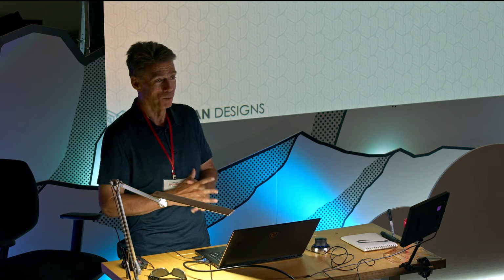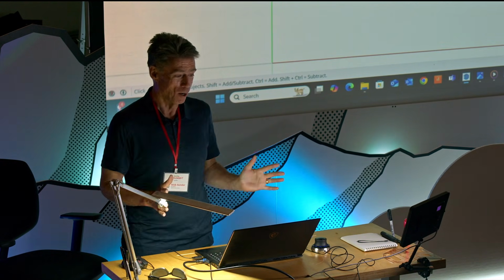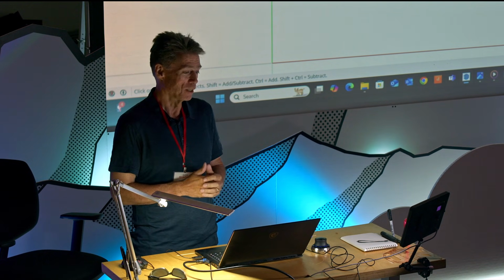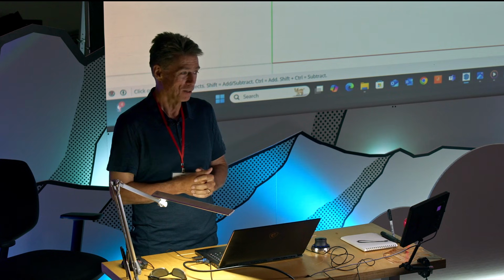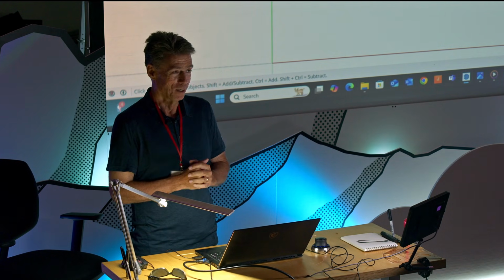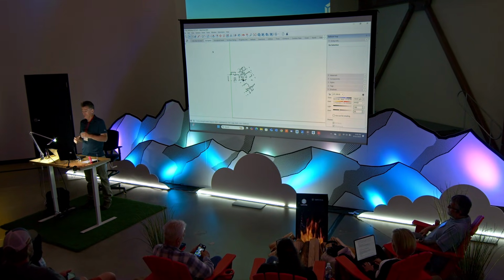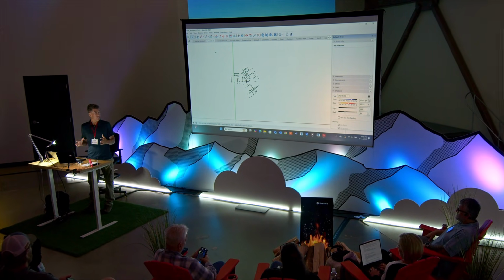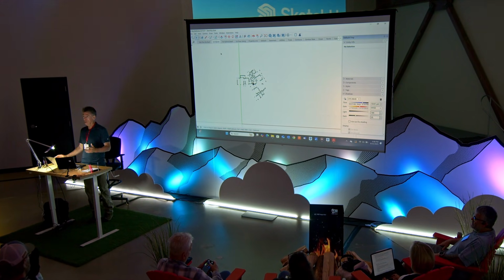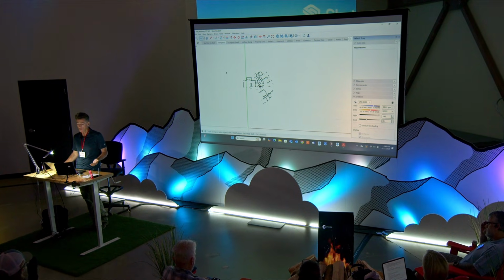Think about how the home is going to be built. When the contractor goes out there, they don't care about anything except the edges of the foundation, where the edge of the stud is, the height of the stud. They don't care about the drywall. They don't care about the thickness of the siding. They don't care what trim you're using at that point. And everything, once they have that frame in place, the rest of it just comes along. It gets applied to it. As the architect, you just need to be aware of anything, like I said, that has special clearance requirements.